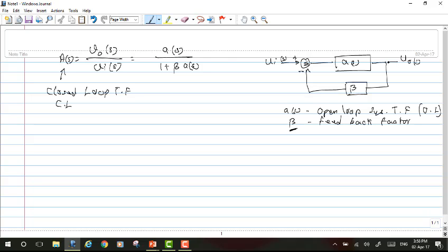So with that introduction, to talk about the stability of the system, I'm going to introduce what is known as a loop gain. This is a term which we'll be using to study the stability of a negative feedback system. Now, to see how this factor, loop gain, or in short LG, determines the stability, let us consider an open loop system having a single pole in it, which is A0 divided by a single pole.